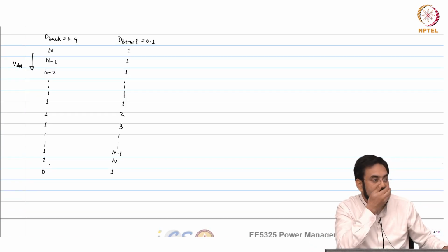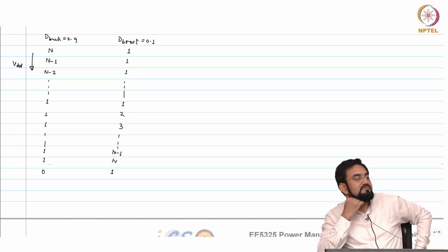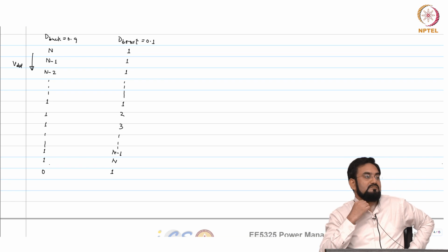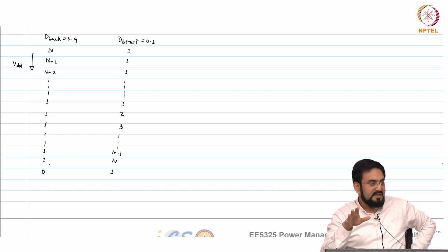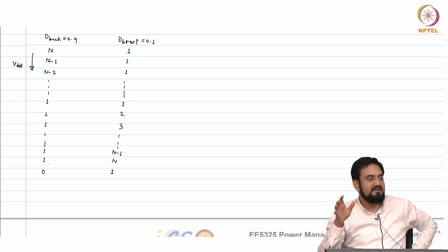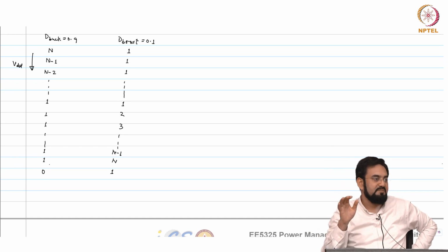Means the problem is why we cannot increase duty cycle after a certain maximum value, that means we can jump to 100%, but at that point the gate driver and all won't work efficiently. Yeah. So, 10% I am assuming is a hypothetical number actually. Nothing special about 10%. If your circuits are very fast and you can achieve up to 98%, then you limit at 98%.